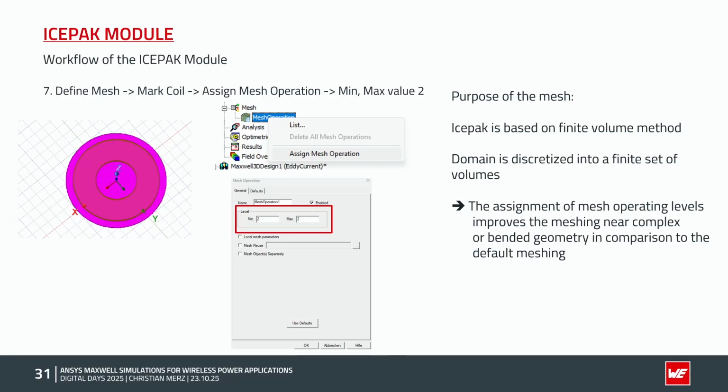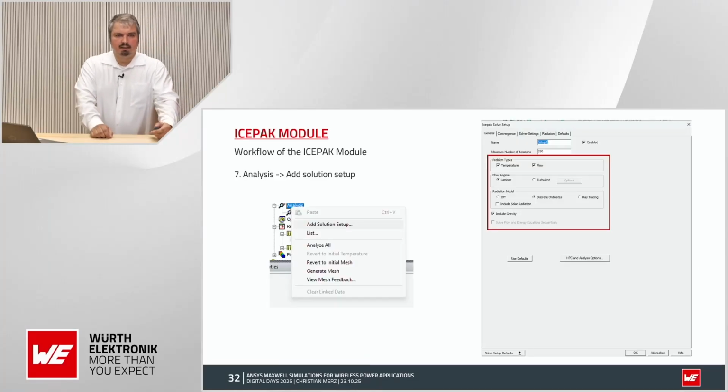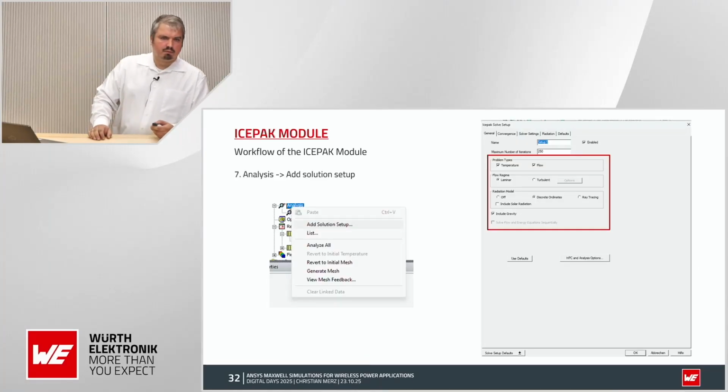Then the assignment of mesh operating levels improves the meshing near complex or banded geometry in comparison to the default meshing, which is very important in this case to get accurate values. Then we just have to add a solution setup.